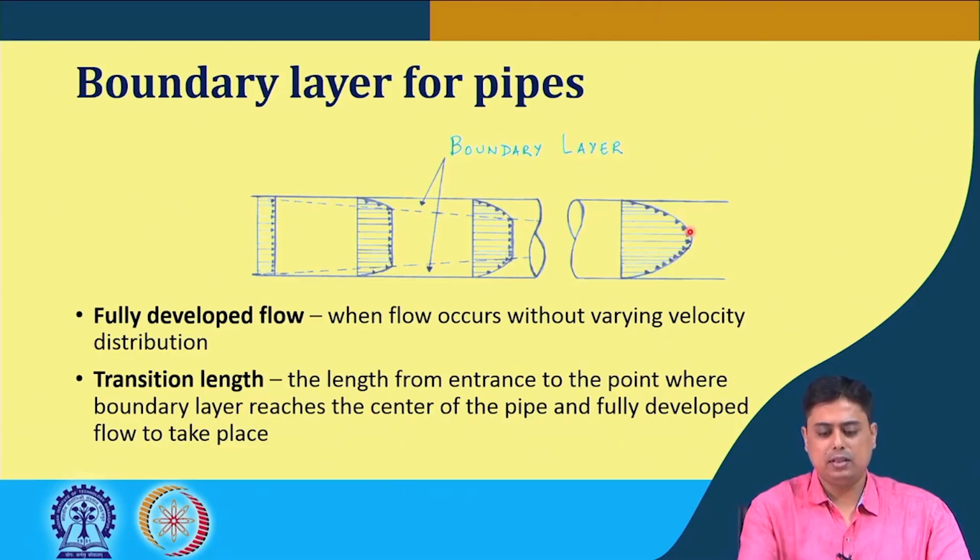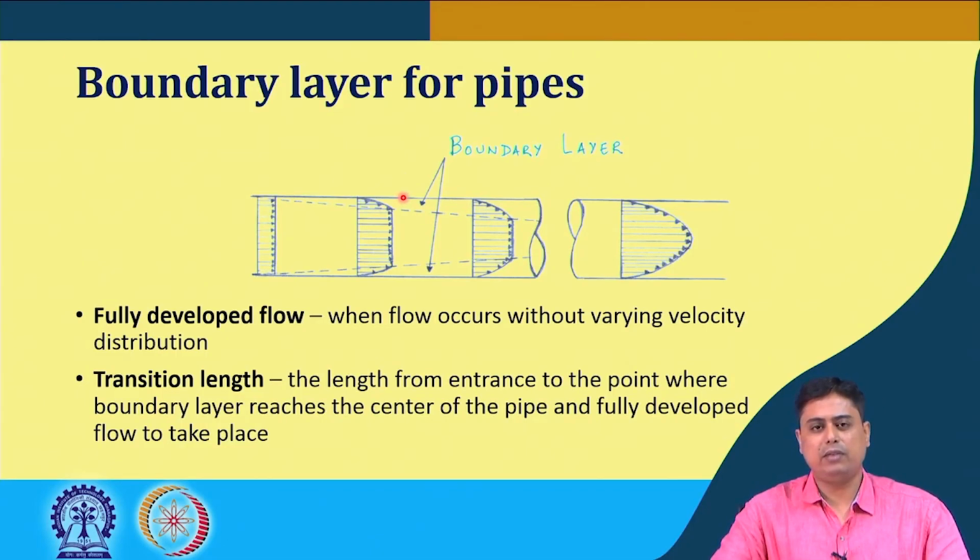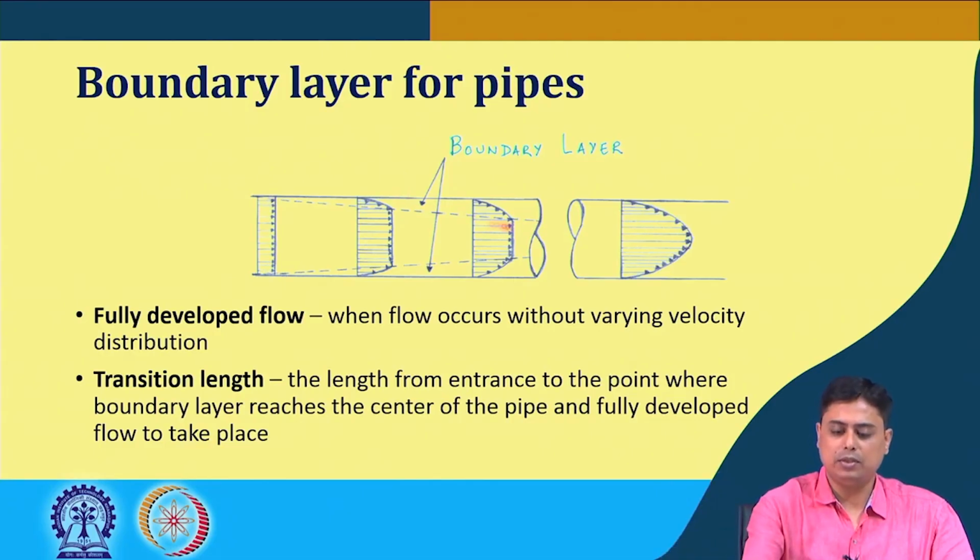So, what happens is that as soon as it enters, the boundary layer starts to develop, and in the developing region, the fluid flows in a rod-like manner, because here the fluid movement is there and here the boundary layer. So, here the flow is very low. As we have seen, in the boundary layer there is a laminar flow or the viscous sublayer, buffer layer, and then the turbulent flow or the flow of the free stream region comes into play.